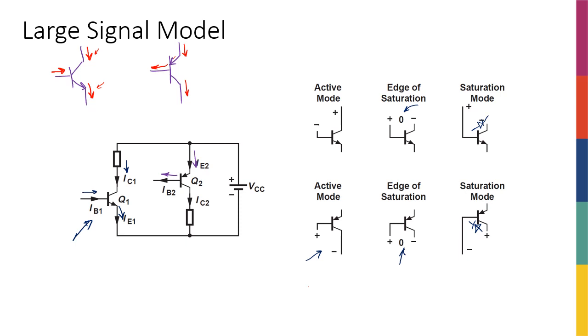Okay, so it's all about knowing that, in terms of equations, the only thing that changed was replacing base-emitter and collector-emitter with emitter-base and emitter-collector, respectively. In terms of current directions, the arrowhead is telling us pretty much everything. So for the NPN, the current is coming to the base and it's always from collector to emitter. For the PNP, it's from emitter to collector. So let me write these down to make sure that there's no confusion. And the current is going out of the base.